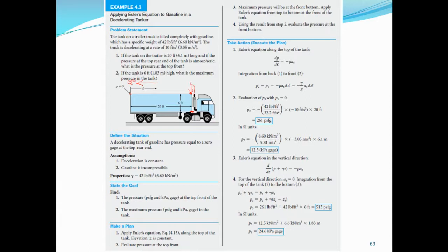Remember that figure where you have a sphere and a stagnation streamline, where we consider a particle which is slowing down, and we say the direction of acceleration is in the opposite direction. And if this is the direction of acceleration, then the direction of increasing pressure will be in this direction. So in this case, you'll have maximum pressure here.